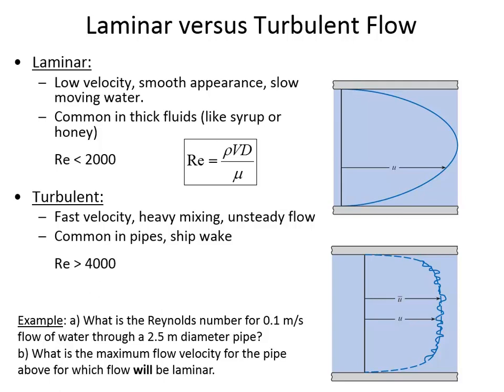The same thing is true if the water is moving turbulent and I gradually start closing the valve, slowing down the velocity. It will stay turbulent until you get to about 2,000. Because it was turbulent before, it will stay turbulent through the transition zone until you get to the point at which it switches over to being laminar. So that no man's land between laminar flow and turbulent flow is determined largely by how you got into the transition zone. Did you get there from the laminar side, or did you get there from the turbulent side?